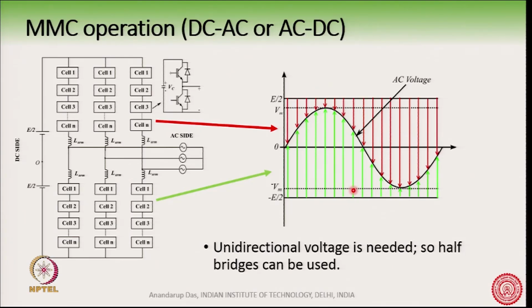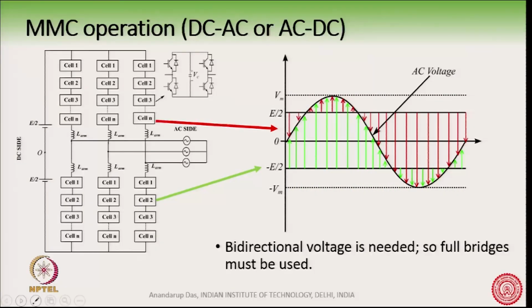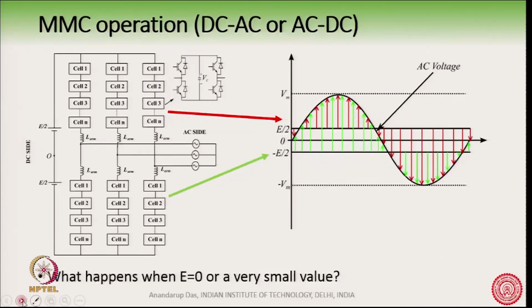So, the same circuit remains, only the arrows flip their direction. It is also possible that the DC bus is less than the peak of the AC voltage magnitude, and in an extreme case we talked about the short circuit in the DC bus.